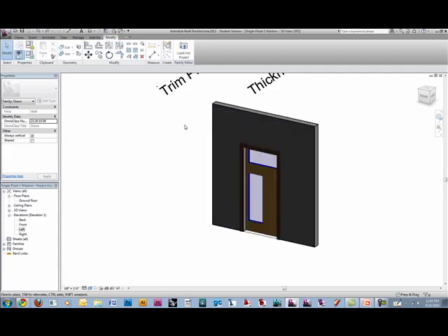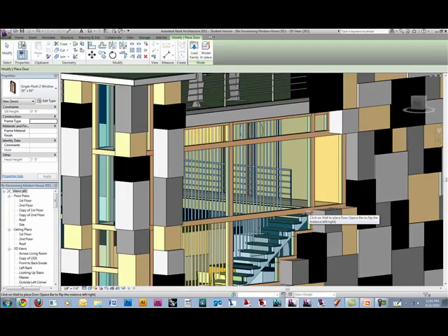Yeah, always make sure you duplicate. Save as, not save. Save as. Duplicate. Yeah, don't overwrite stuff. You'll be in a world of trouble, and then you'll have to get it all back. I've seen some really messed up projects where people have just ruined all the out-of-box stuff on Revit, and then they end up having to delete Revit and reinstall it because it's so messed up you just can't get it back. So I'm gonna load this in a project now that I've renamed it.